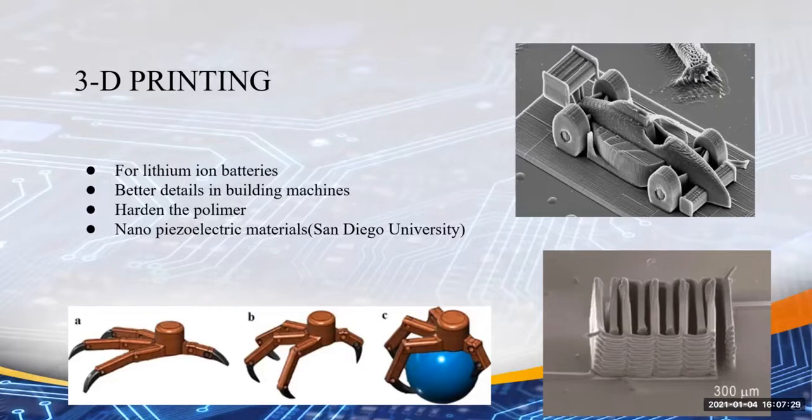And actually, at the beginning of the presentation, what I tried to say, as we see in the picture, is that 3D printing can now be used to print lithium-ion microbatteries the size of a grain of sand. These are made by Harvard and the University of Illinois. Printing three-dimensional objects with incredibly fine detail is already possible using a direct laser writing method called two-photon lithography. At the University of California San Diego, they fabricated 3D piezoelectric materials that rely on piezoelectric nanoparticles embedded in a matrix.